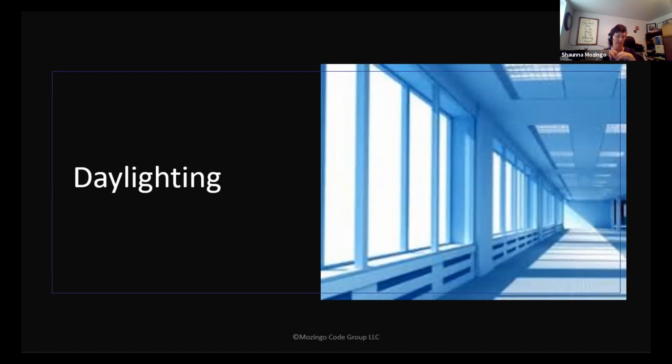That's what it's trying to tell you. The daylight control needs to be configured to not be set above the unoccupied set point, so that it doesn't turn the light on just because there's no daylight when the occupancy sensor has turned them off because there are no people. That's what that's trying to say.